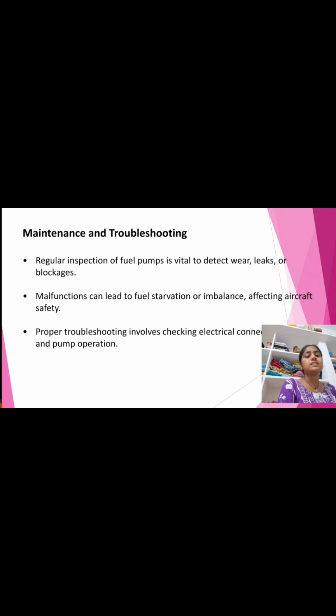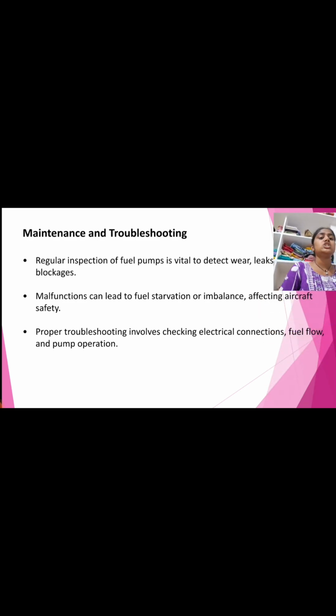Maintenance and troubleshooting: regular inspection of fuel pumps is vital to detect wear, leaks, and blockages. Malfunctions can lead to fuel starvation or imbalance, affecting aircraft safety. Proper troubleshooting involves checking electrical connections, fuel flow, and pump operation.